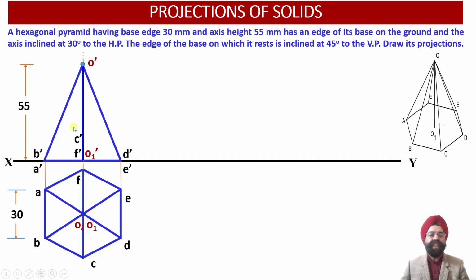the front view. Similarly, the hidden line projections corresponding to the slant edge O dash F dash have been covered by the object line projections corresponding to the edge O dash C dash. We can see the OC edge has superseded the edge OF over here.